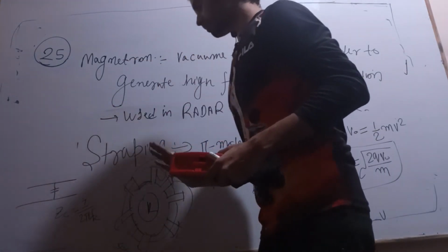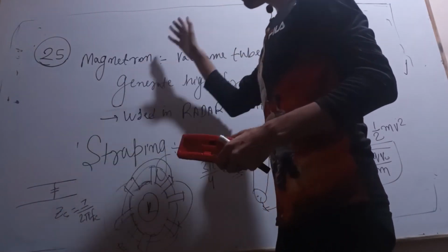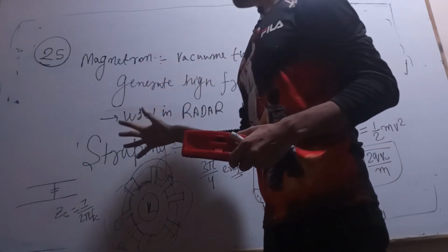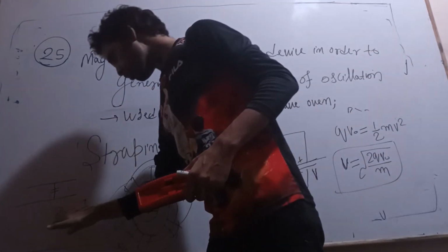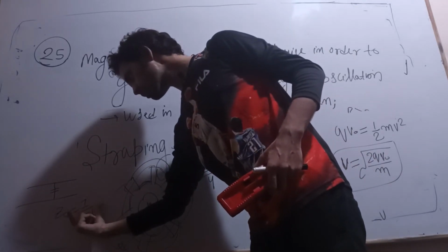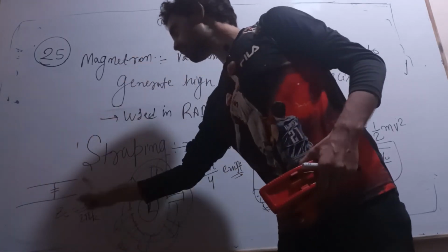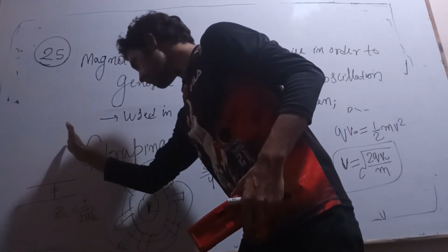This impedance decreases. If the frequency is so high, in the order of gigahertz, because the frequency used in a magnetron is in the order of gigahertz, 0.6 to 30 gigahertz, then at that frequency the capacitive impedance is zero, which means it is shorting. Yes, it is a short circuit.